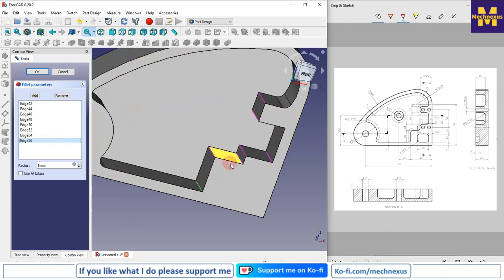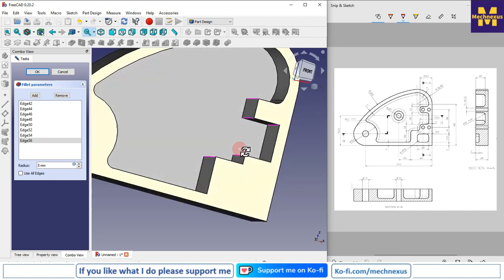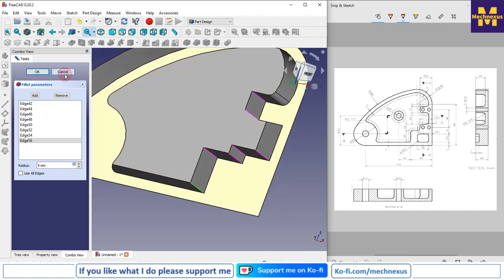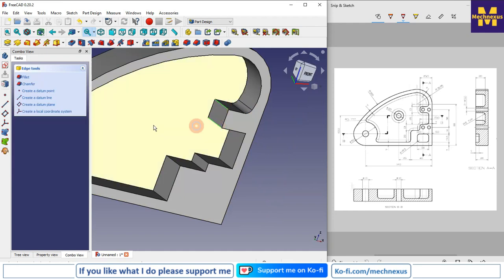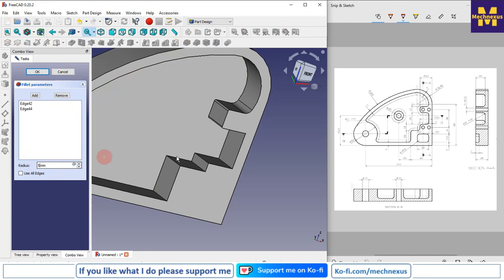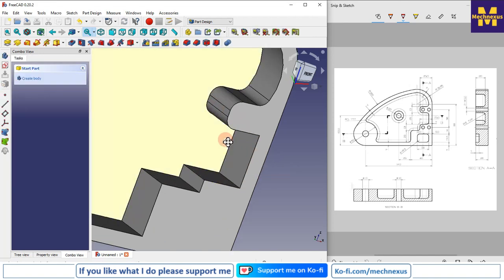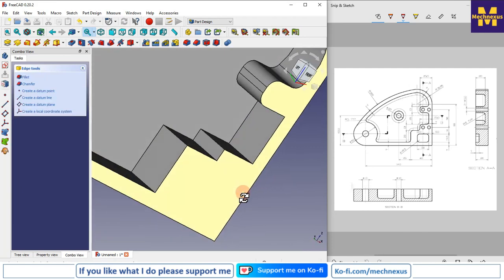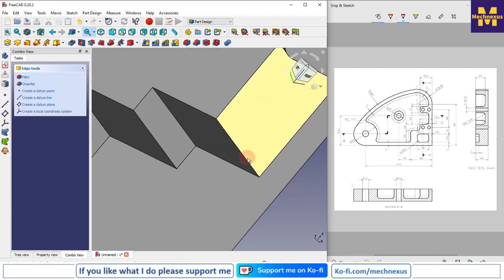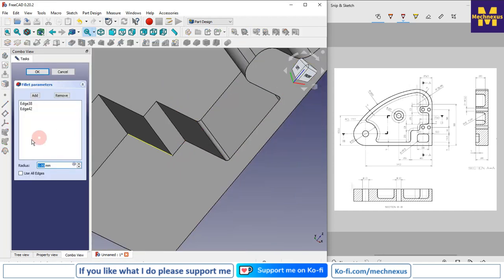So why it is creating the problem, I'm not sure. So instead of selecting the multiple edges, we will do it in parts. So select these 2 and give the fillet. Okay, here it is taking. Now select these 2, select fillet.